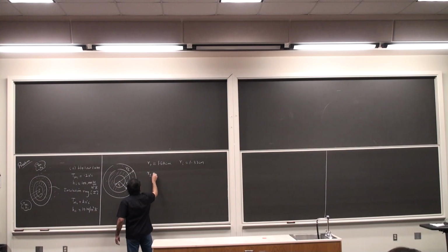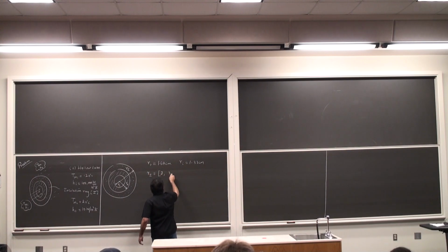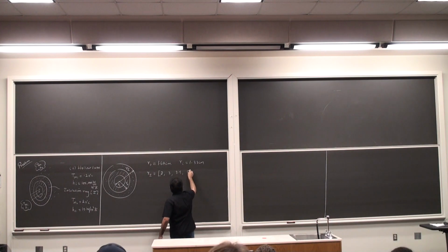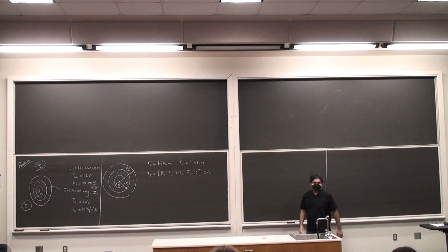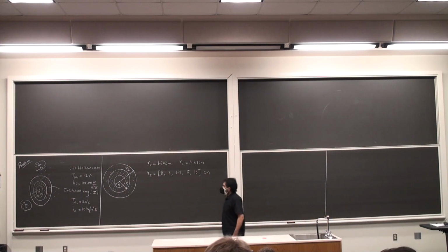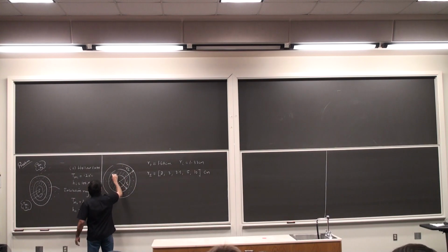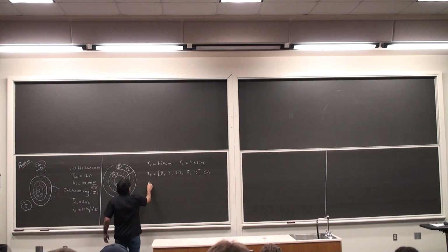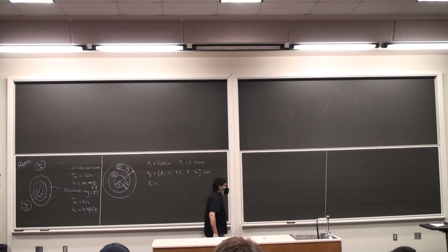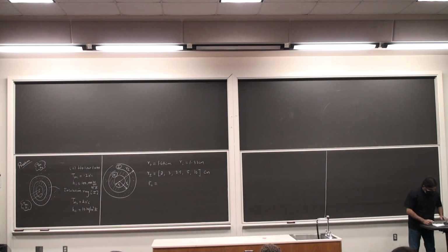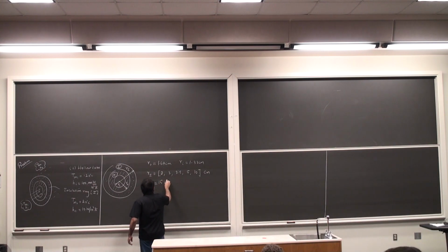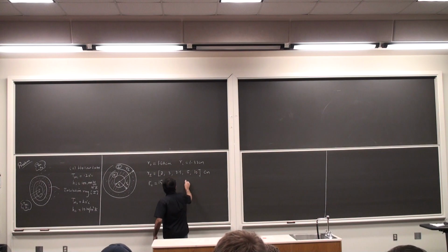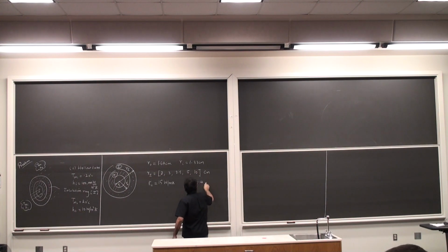So R capital I starts at 2, 3, 3.5, 5, 10 centimeters. Thermal conductivity, so this is material T, tube, insulator I, KT is some value, approximately 15 watts per meter Kelvin. And Ki is 0.4 watts per meter Kelvin.